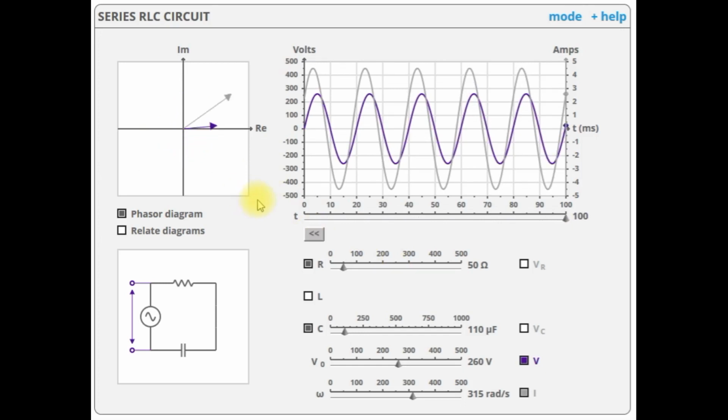maintained always. So if you have these two sinusoidal waveforms, one is represented by say e is equal to Em sin omega t, and another is represented by say i is equal to Im sin(omega t plus phi), because in this case the current waveform is leading.